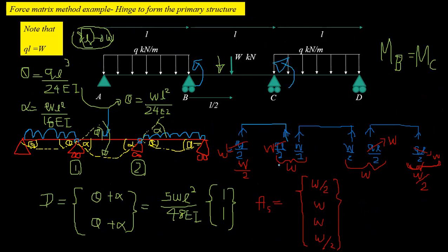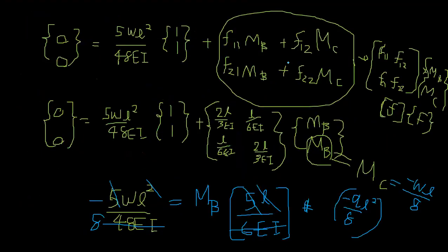So we took clockwise positive for this part. So that means the other half, it's anti-clockwise, the same bending moment. We only just considered this one, right? So we obtained this is negative. So that means here it's anti-clockwise, right? So once you know F, you can go ahead and find actions as well.